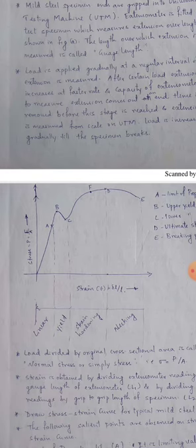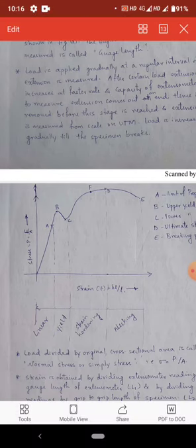The region C to D is strain hardening, because as the load increases, the strain also increases, and the stress also increases rapidly. Therefore that zone is strain hardening. When the point reaches D to E, failure takes place, that is the failure region, under the necking region.